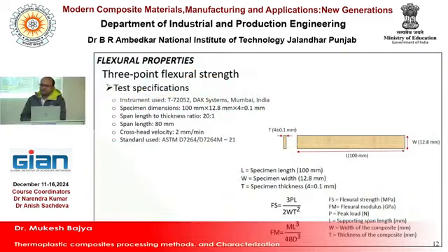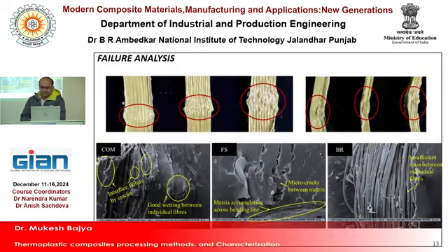So these are the failure analysis after the destructive testing, and then you can confirm what is happening, which kind of failure is happening. According to that, you need to tune your pre-packs, and you can also change the composition of the reinforcement and the matrix.